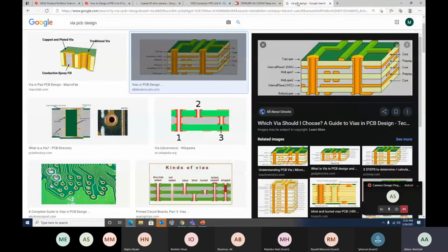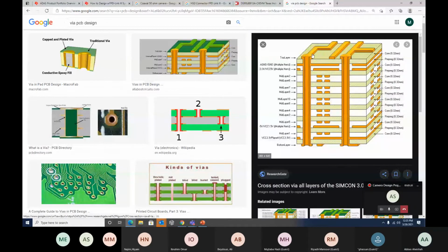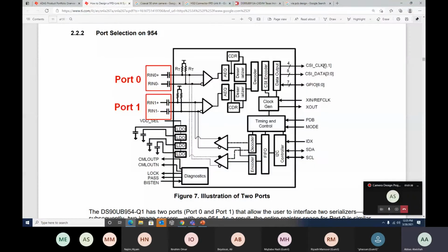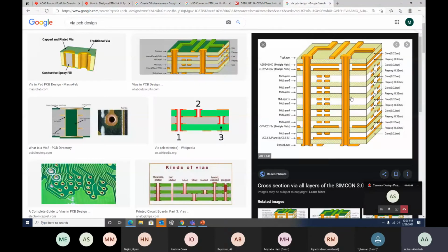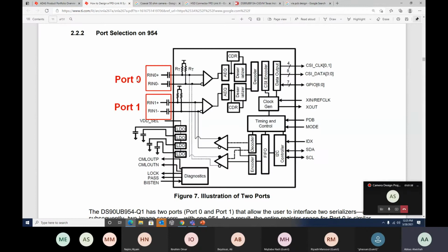So the VIA here, having a VIA, if you have a scope, you would tap into the VIA right here, and then look at the output, measure between them, right? So the design board we're making, we wouldn't go with the first design board and take it to production. We would have these VIAs there. And why would we have these VIAs here? Have a VIA here, and others where we have inputs and output.